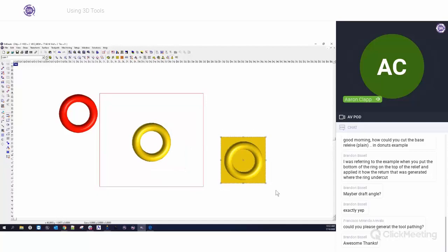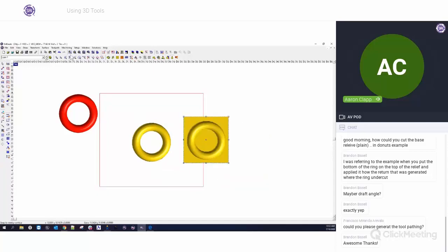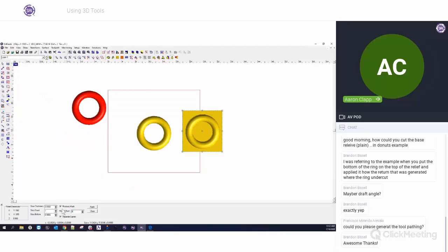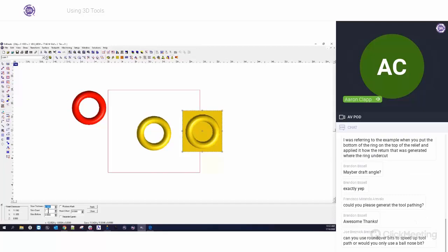But essentially, what I did here by going to extract slices, this is your quick and dirty version of it. Go to extract slices. You remove all these objects. Set it to 1. And then all you have to do is set it to the maximum thickness. When you set it to the maximum thickness, slice count 1, the software automatically knows what you're wanting to do. It basically understands, oh, he's wanting to do 1 slice, the entire thickness of the object. What he wants to do is slice off that no thickness relief, and that's how you do that.